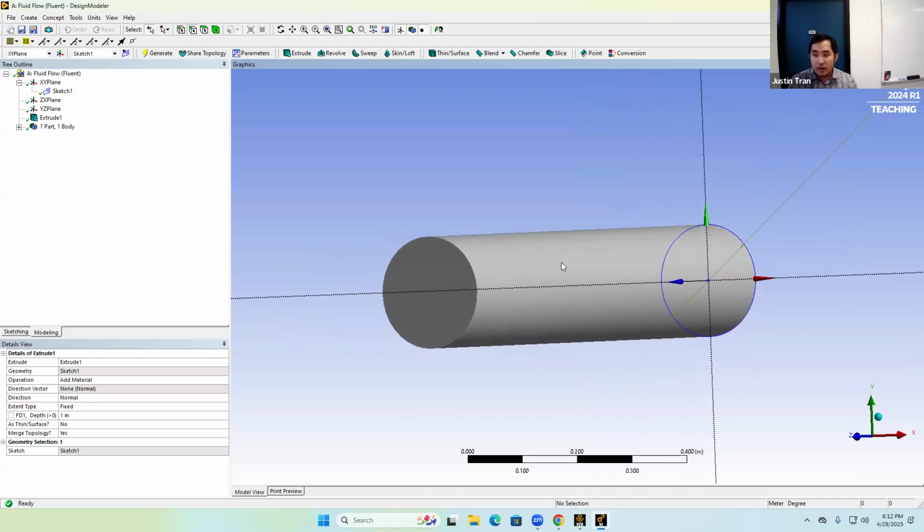All right. Any questions on the geometry construction here? Okay. And remember, we are making a geometry of the region where the fluid is going to go. I know this looks like a solid cylinder, but this is the region where the fluid is going to go. So imagine that there's a pipe around the outside. The pipe on the outside defines the solid part, and then we're making a mesh of the fluid part.